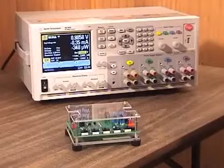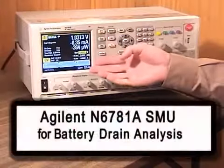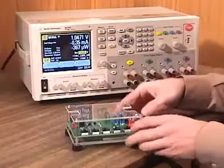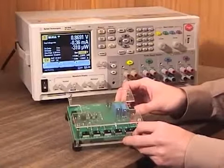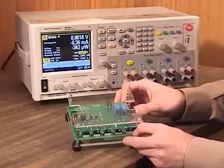Now let's take a look at the new Agilent patented feature we call seamless measurement ranging. Today's test setup consists of a demo board connected to the new N6781A 2-quadrant SMU for battery drain analysis. This demo board will simulate the dynamic current that is typical of a battery-powered device as it transitions between states of operation. This type of dynamic power management is used in many battery-powered devices such as mobile phones, e-book readers, and medical devices where power consumption is critical.